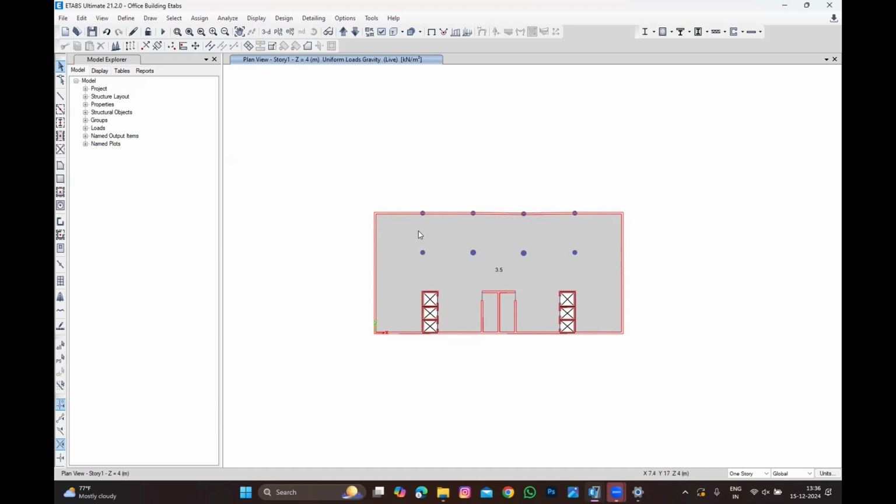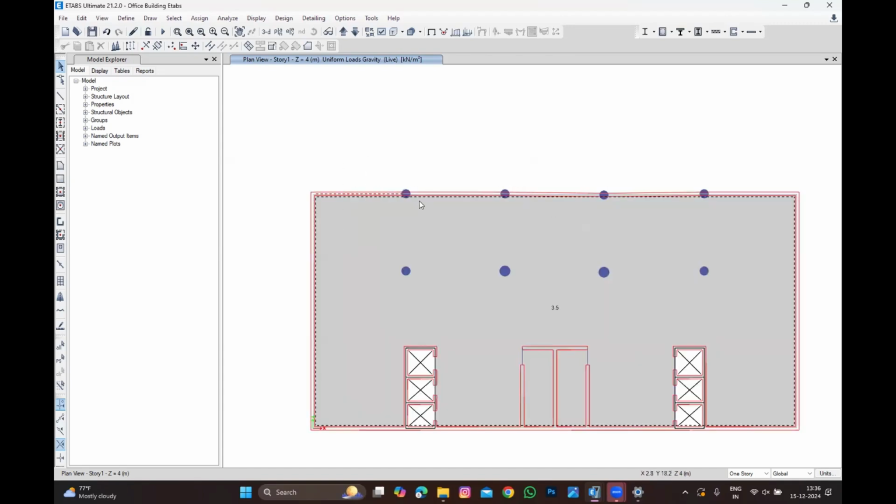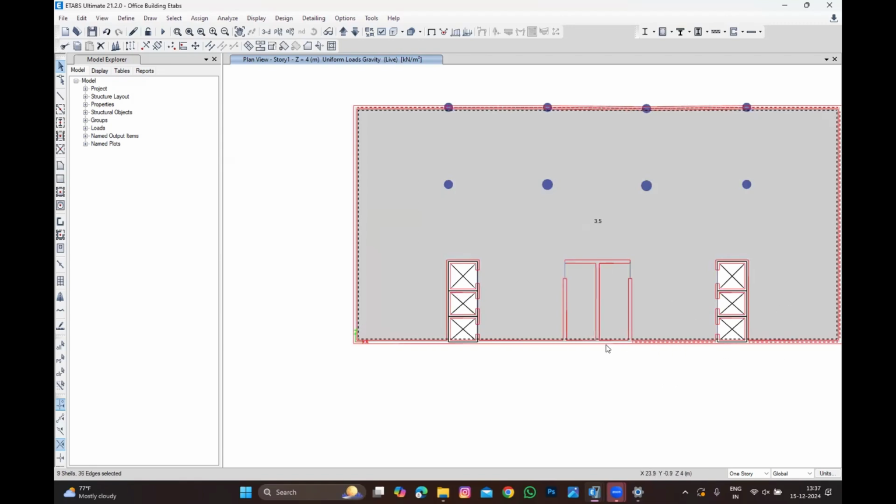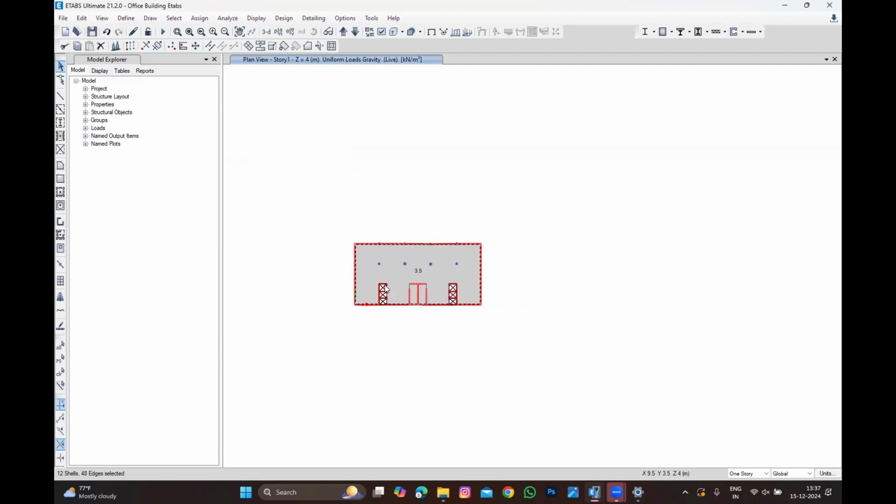Now what I'm going to do is remove the wall, even the slabs as well. The wall is only the retaining wall. Because I'm talking about story one, up to ground floor the retaining wall will continue. Ground floor in the sense that the retaining wall will go down. That's how the software will treat it. Ground floor is nothing but below basement to ground floor. So in story one, delete all the retaining wall. Gone. Let it be, because I'm going to model the beams here.